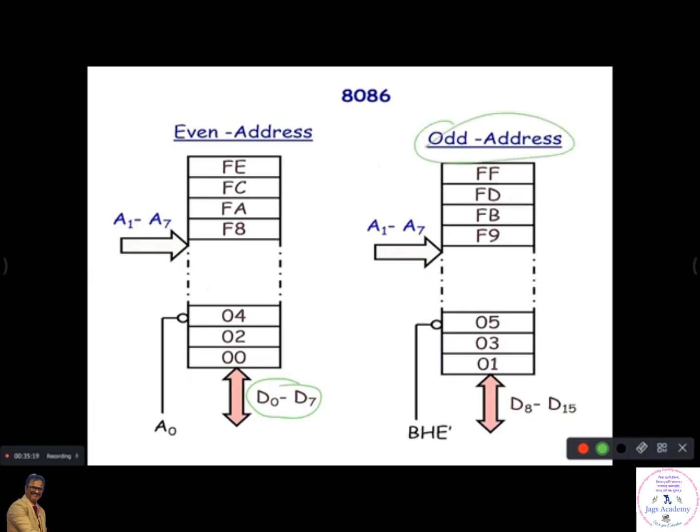So whenever you design an I/O interfacing, if you want to read 16-bit data, the data transfer has to be arranged in such a way that the device will have two port addresses and will give 16-bit data from the two addresses.